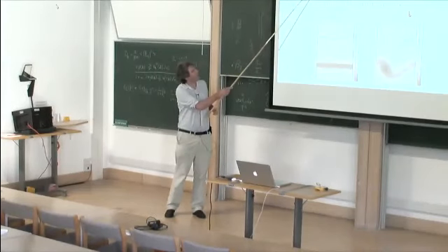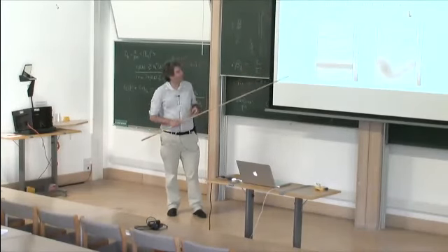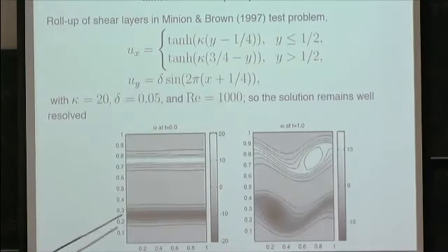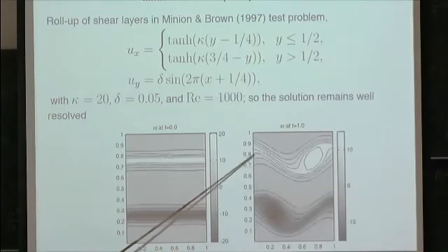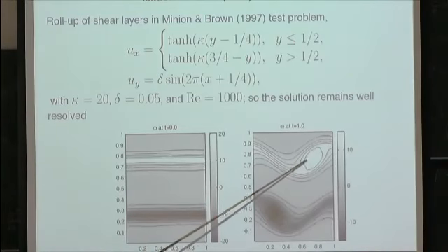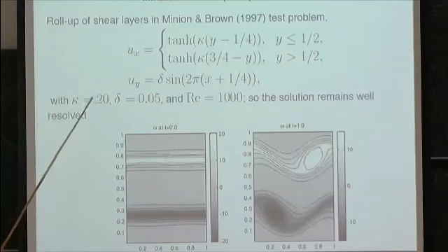So their initial conditions are two anti-parallel shear layers which are perturbed with a little bit of a wiggle. So here are two fat shear layers, and they're slightly perturbed. So which way up is it? That was going up, that's going down slightly. So when you let it evolve, you get a Kelvin-Helmholtz instability, so you stretch out shear layers here and you roll up into two big fat vortices, when you start with fat shear layers and lowish Reynolds numbers. This is just a 2D Navier-Stokes problem.